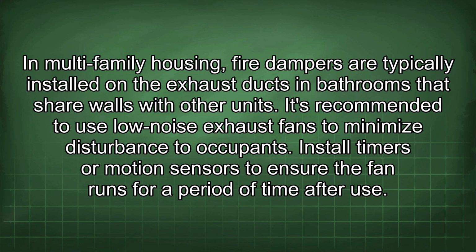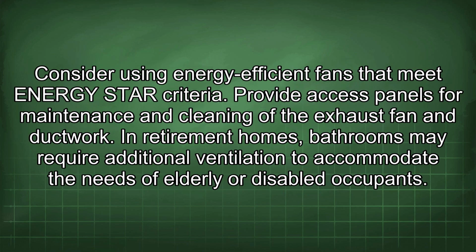It's recommended to use low-noise exhaust fans to minimize disturbance to occupants. Install timers or motion sensors to ensure the fan runs for a period of time after use. Consider using energy-efficient fans that meet ENERGY STAR criteria. Provide access panels for maintenance and cleaning of the exhaust fan and ductwork.